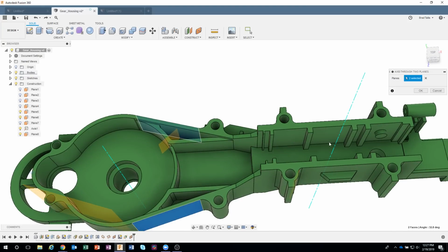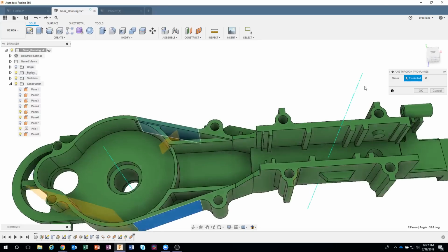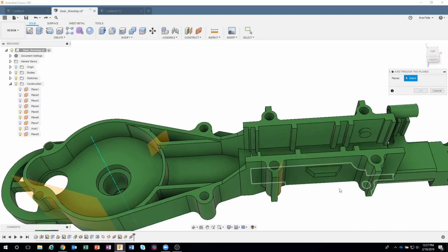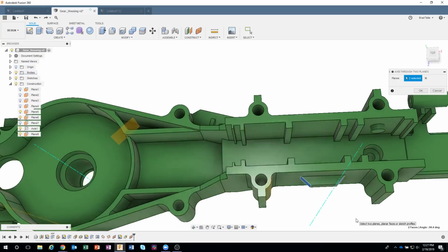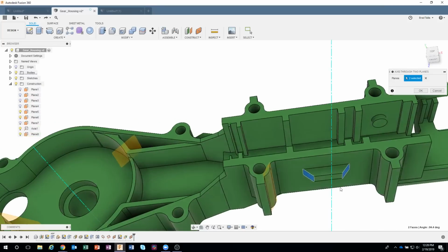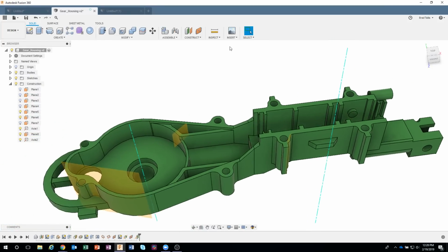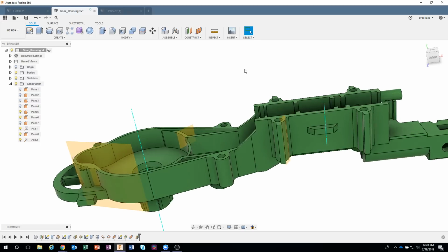And maybe for aesthetic reasons, we want to put something here and it lines up with that angle. So this is a useful tool for creating something that slices through 2 planes. So again, I could say here, and it's going to create an axis out here, which I could then use to reference. Okay. And I'll shorten that guy up because it doesn't need to be quite so big. There we go.